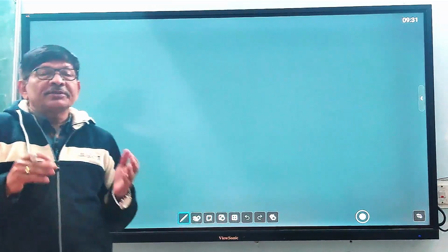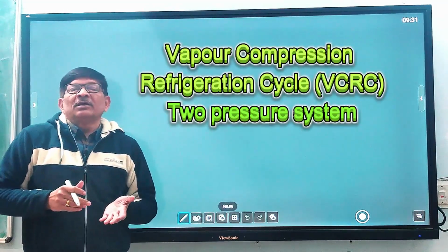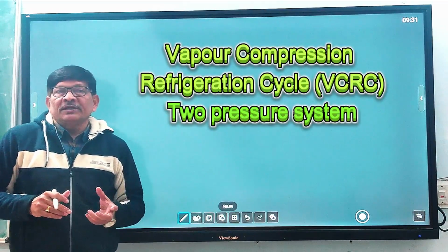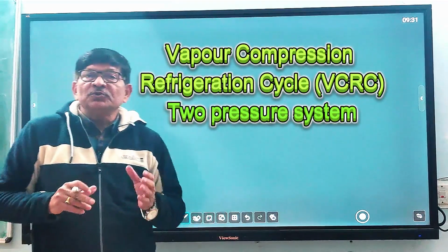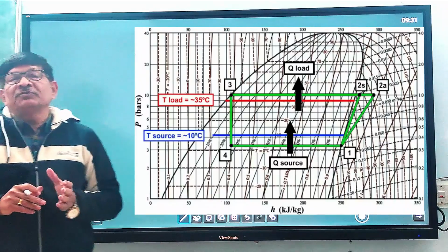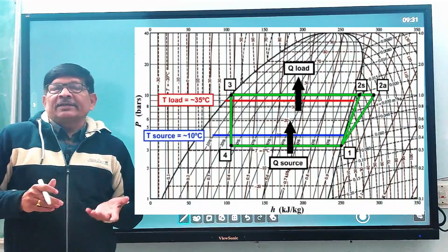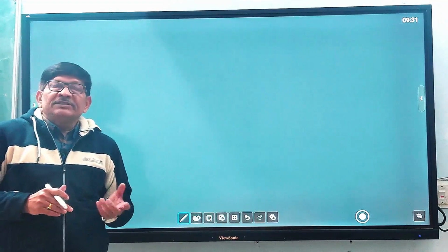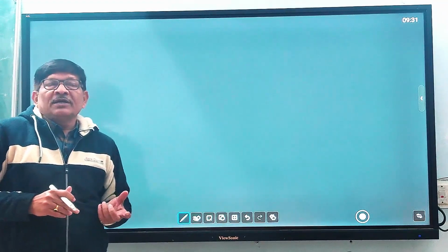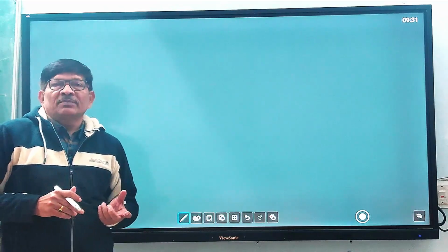Today we are going to discuss the vapor compression refrigeration cycle and the pH chart, the pressure enthalpy chart. How we can use the pressure enthalpy chart to solve problems of the vapor compression refrigeration cycle. As we know, the pH chart or temperature enthalpy diagram are useful for solving the problem of vapor compression